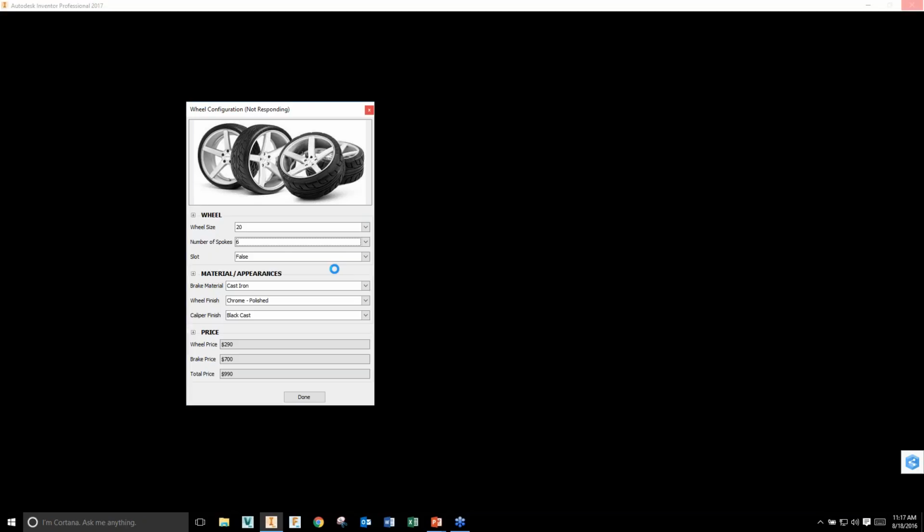And so what you're seeing here is I'm going from a number of spokes of 9 down to a number of spokes of 6. And that goes back to that rule where I've just gone into the CAD model via some code and basically said, hey, in this circular pattern, go from a value of 9 to a value of 6. And what's happening is Inventor in the background is just rebuilding this model. Right? Same thing below that.